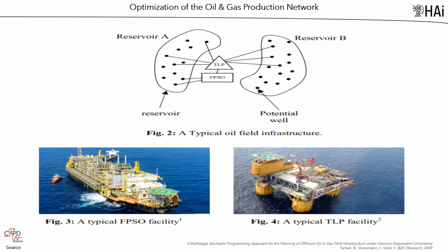There are two options for drilling wells. Each well can be drilled either as a subsea or a TLP well. Drilling ships are used to drill subsea wells, so there is no need to have a facility present to drill a subsea well. Unlike subsea wells, a TLP well must be drilled by a TLP facility. Due to economic reasons, each type of well is drilled in groups consisting of a fixed number of wells.